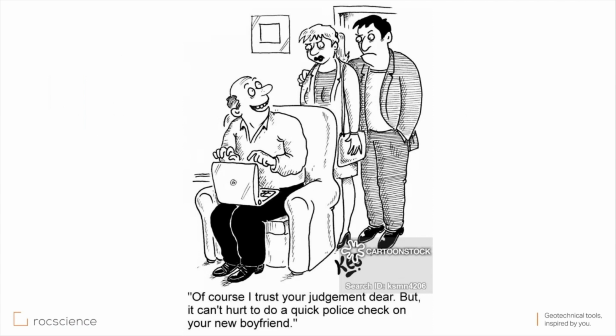Of course, I trust your judgment, dear daughter, but it can't hurt to do a quick police check on your new boyfriend. So what happens is, even though you have your rigorous methods and they give you results, you want to be able to check them. And the Bishop is a good check. So Bishop will allow you to see whether the rigorous solutions have converged to the critical mechanism or not.